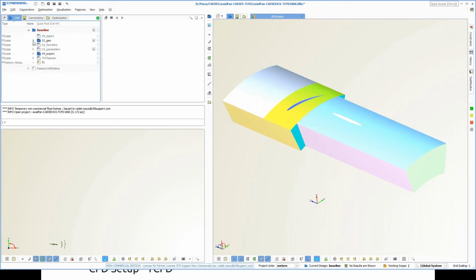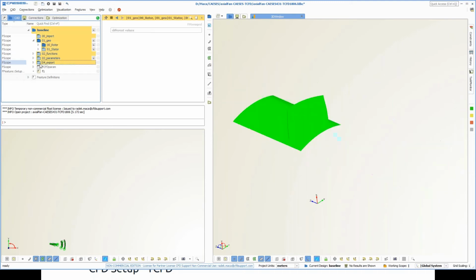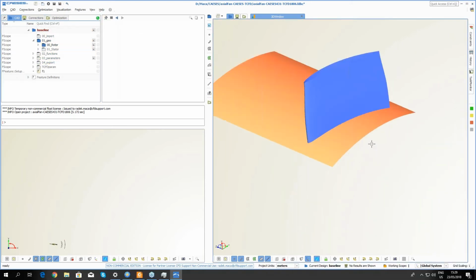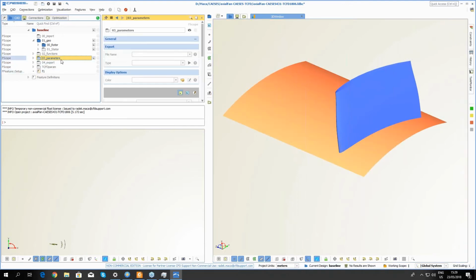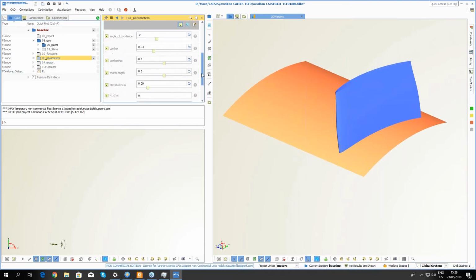The beauty of the CAD here is that everything is based on the dependency modeling approach. So basically everything is connected, and when you change one parameter, the other parameters are changed as well, and the geometry will never break up. I just want to show you some nice images, so I can visualize the rotor part. Here are the parameters preset. There are 6 parameters to be optimized.